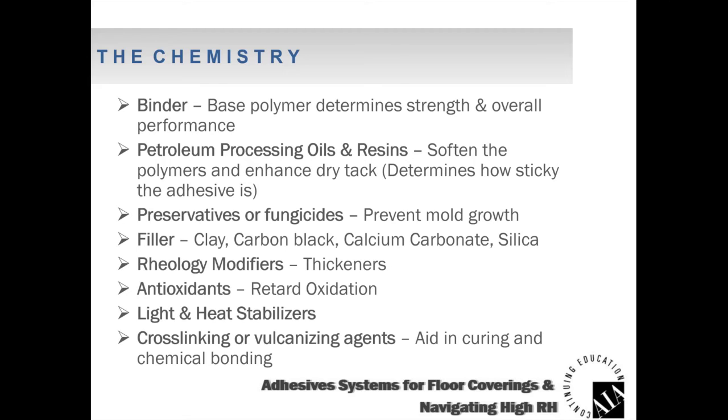There are also rheology modifiers in there, depending on what you want the viscosity of the adhesive to be. Maybe a flooring adhesive is a lower viscosity material compared to a wall-based adhesive, where you want something a little more heavy-bodied for applying it to a wall, so that gravity isn't taking over and having the adhesive come off the wall.